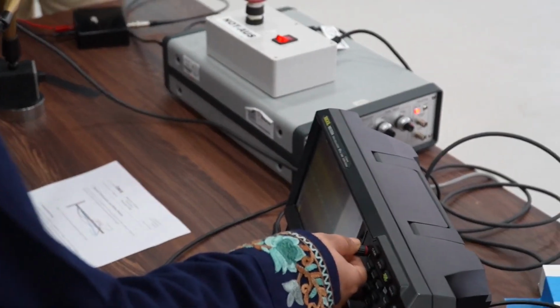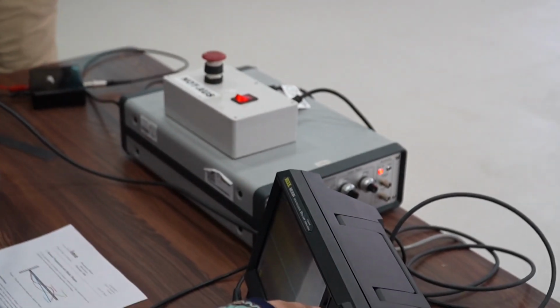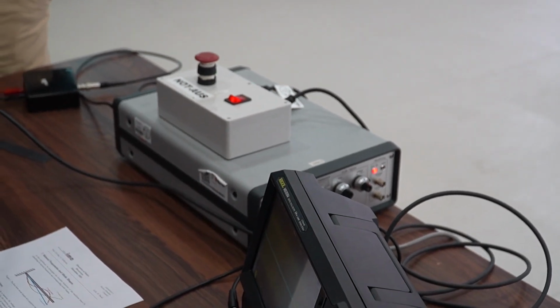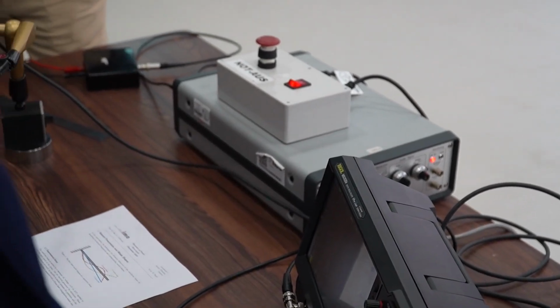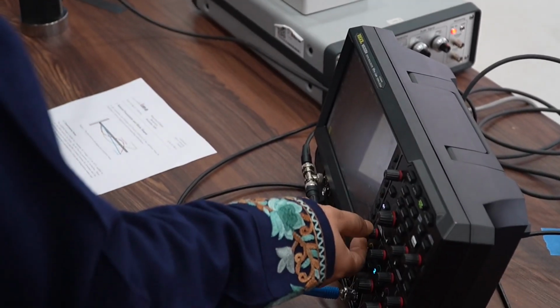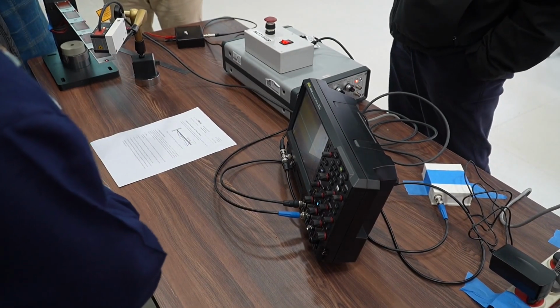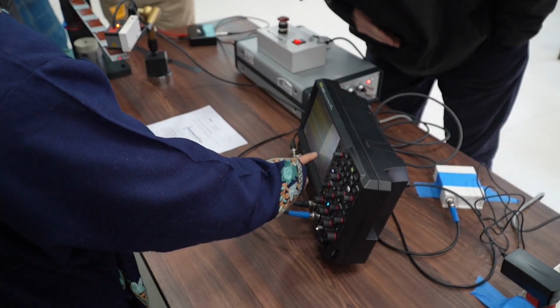Okay, but I don't see that you excite at any eigenfrequency right now, right? So let's do that. Yes, go for it. Start. Maybe we shut the cursor. And now go to the function generator and set it to somewhere below the first eigenfrequency. Use a sine somewhere below the first eigenfrequency and don't exceed the control voltage. You may now exceed the control voltage to not 0.1 but more like 0.2. Exactly.